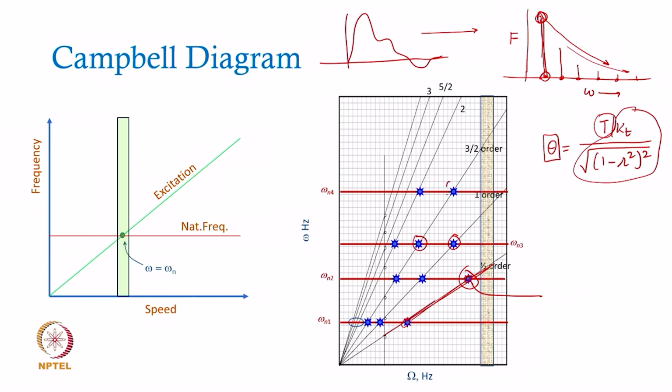But look at these ones, they are the third ones. The third one will have much lesser amplitude. So, your T3, if you are trying to evaluate theta 3, the third component of the total twist, that total twist will be contributed by the first harmonic twist, the twist due to the second harmonic excitation, the twist due to the third harmonic excitation.